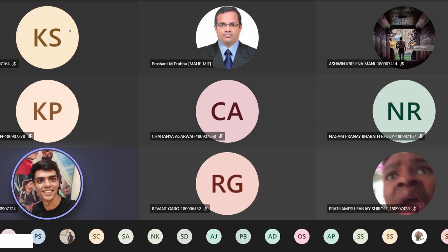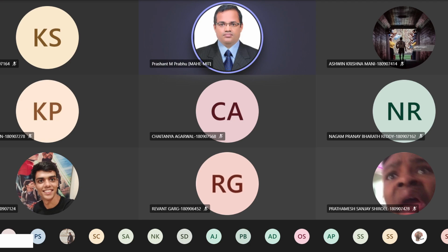In delta modulation, agreed that the quantizer only uses 1 bit at a time, but you also have to sample at 10 times the rate, like you said in the example you gave. That is what is required. But if I have say 1024 levels in PCM, how many bits do I need per sample? 10 bits per sample.